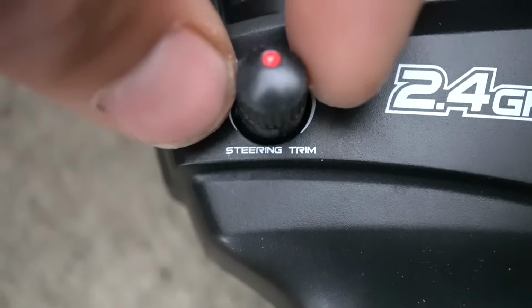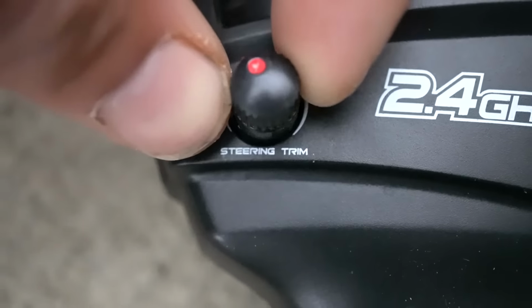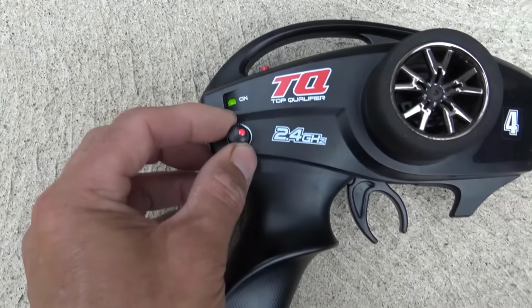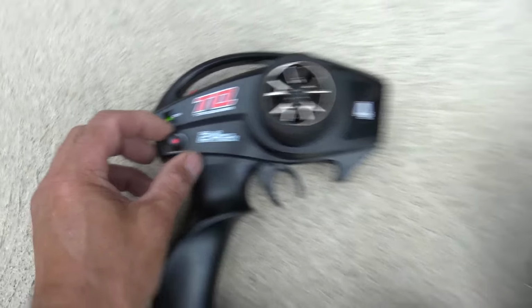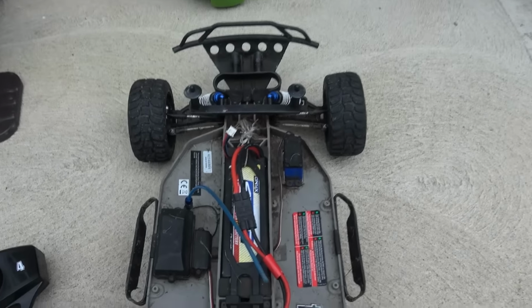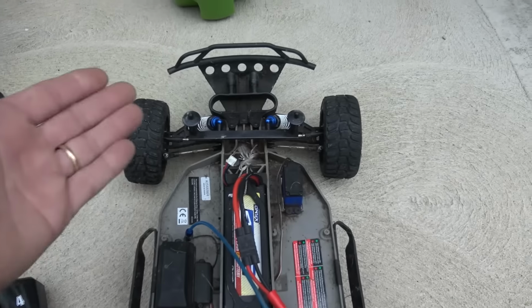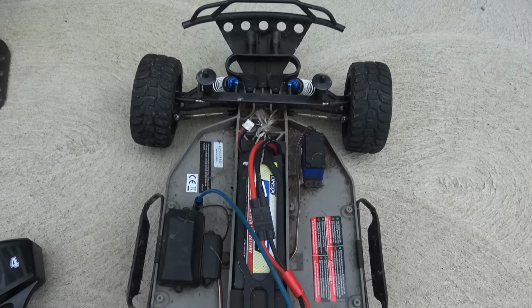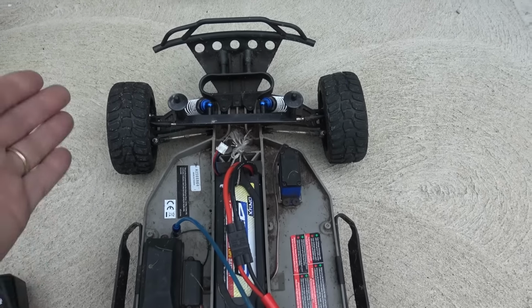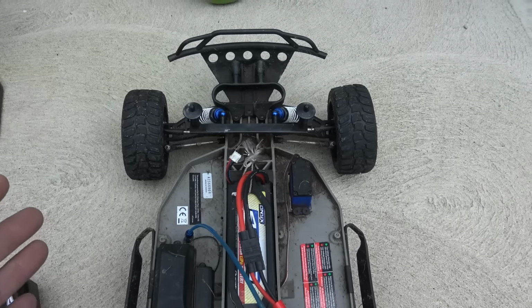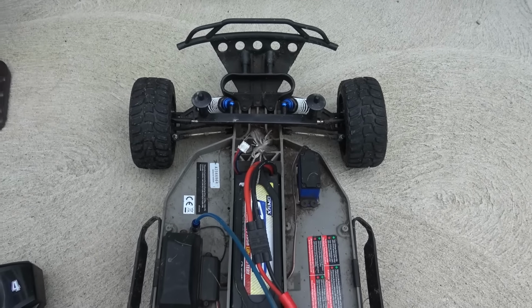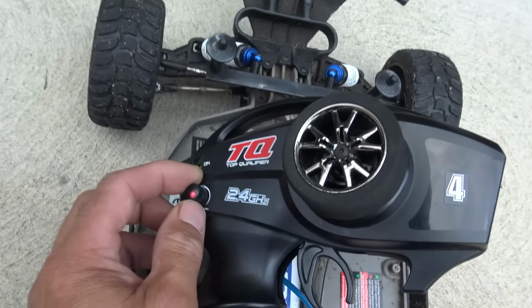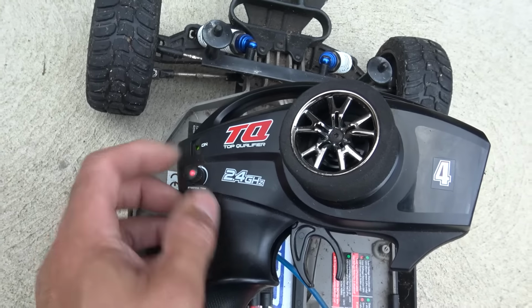There's a steering trim adjustment on the controls of it. Now, why do you think we have this trim adjustment? Well, I'll tell you what. In a perfect world, with the wheel straight ahead, which this thing self-centers, the vehicle will go straight down the road. But what happens is, life happens. We bang into curbs. Nothing is quite as it should be. Things get out of whack. That's why we have this trim adjustment here to make adjustments.